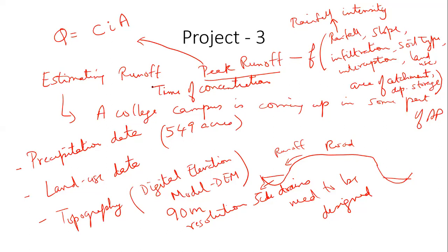So, for example, in our permanent campus at IIT Tirupati, since we are at the foothills of the mountain, whatever rainfall falls on the mountain will actually flow into our campus, right? So we've actually kept gaps in the compound wall. All around the campus, we have the compound wall, or the boundary wall. At some locations where there's a natural stream, we have left a gap under the wall so that the water can flow in. If you try to obstruct that water, it will put pressure on your wall and your wall may overturn and so on. So therefore, we have allowed the water to go through, right?